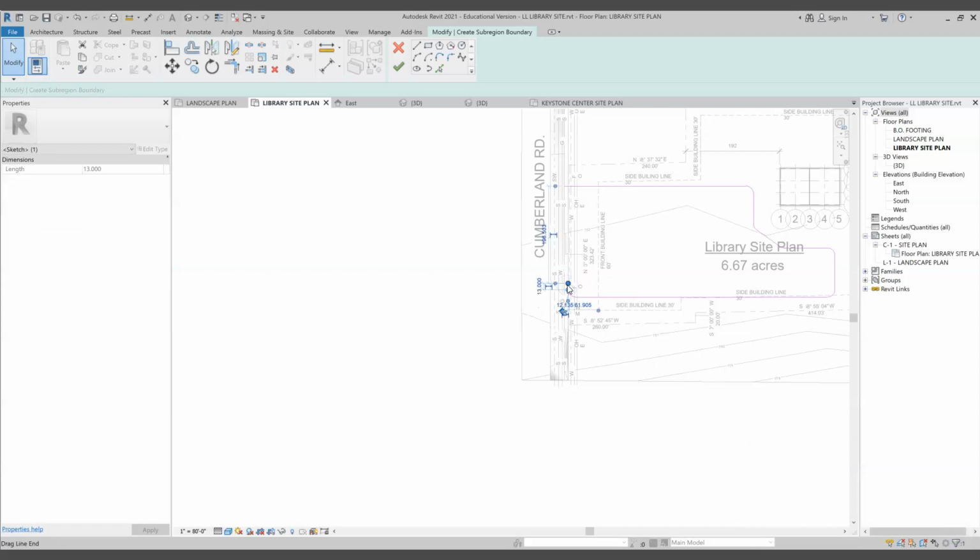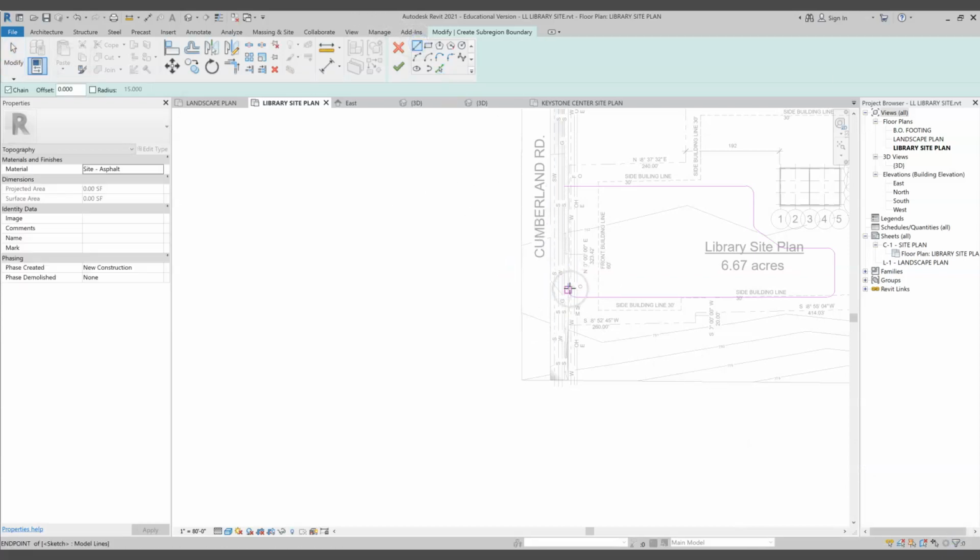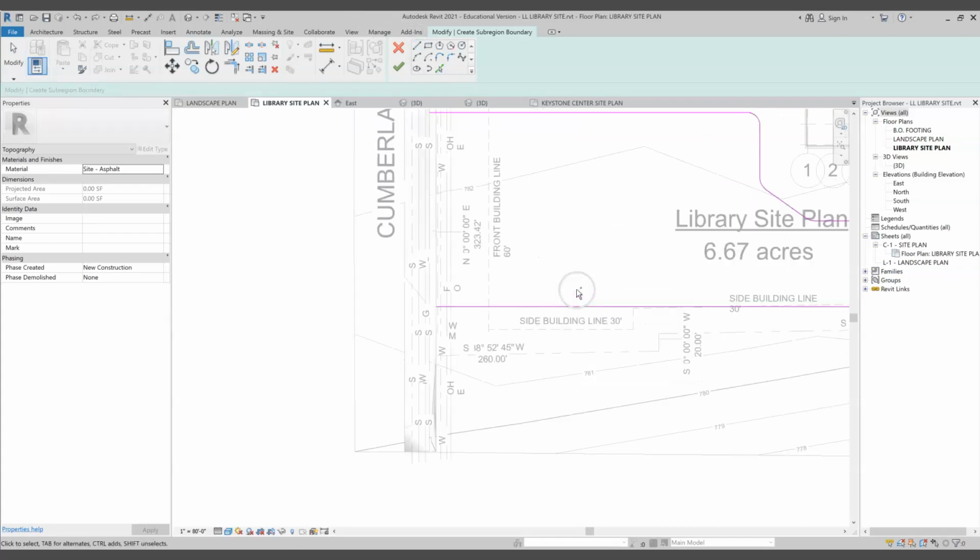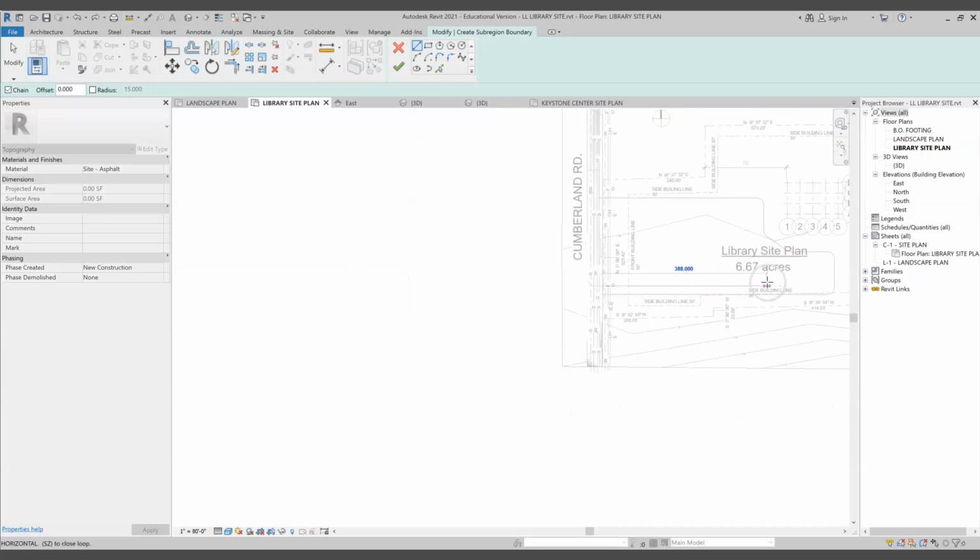Okay, so we're going to go drawing the lines here. We'll add the fillets in afterwards. So I'm going to hit Control Z. And now I'm just going to do lines because it didn't like that sharp turn. Okay, so here we go. Just pick a width. I'm going to say this street's 20 feet wide. This is the exit from the drop-off. And then I'll go add the fillets in afterwards.